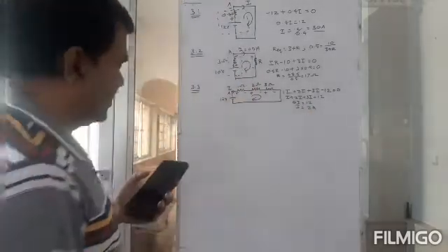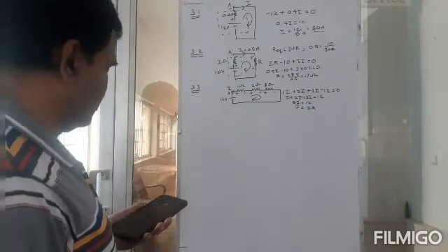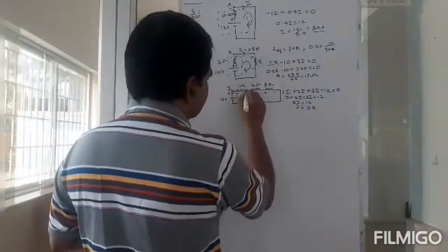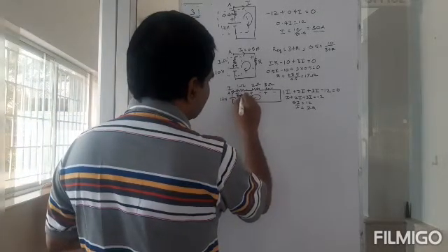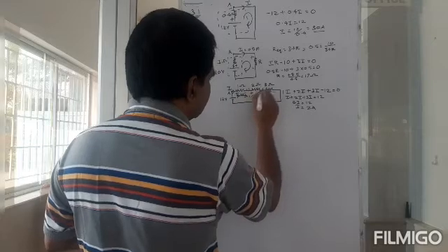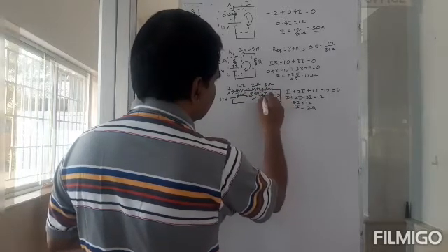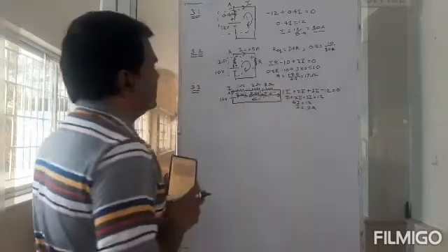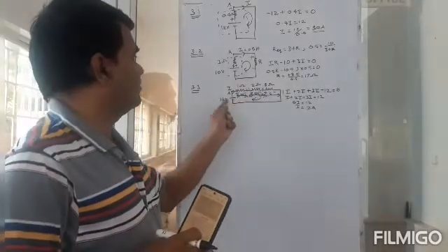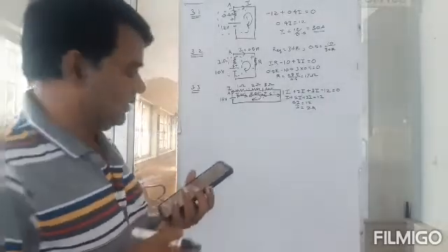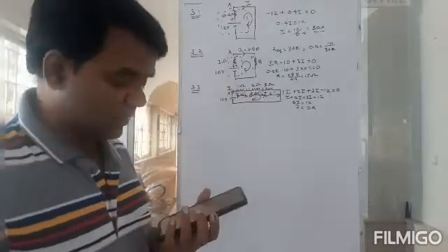Okay, it's very simple to do. Okay, then if I is equal to 2, then what is the potential drop? It will be 2 volts, and I into 2, this will be 4 volts, and this will be 3 into 2, 6 volts. You can see the 2 plus 4 plus 6, again 12, so 12 minus 12 should be 0. Okay. So that's how we do this problem.